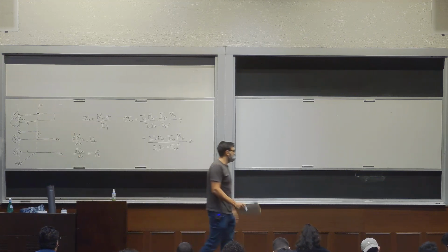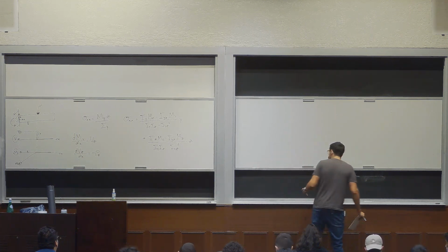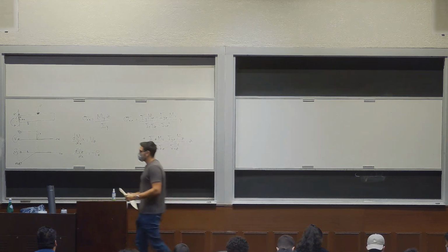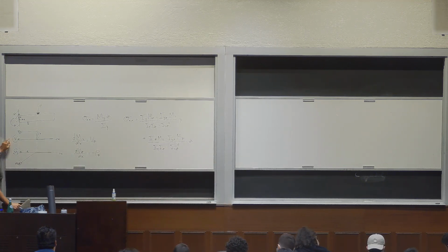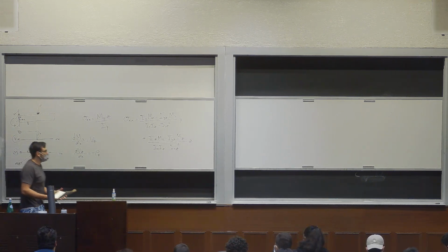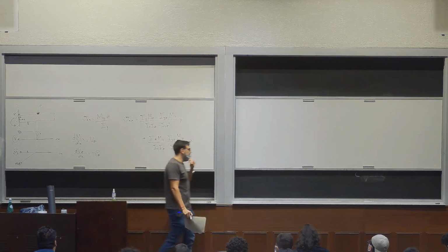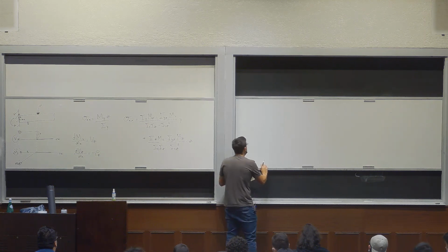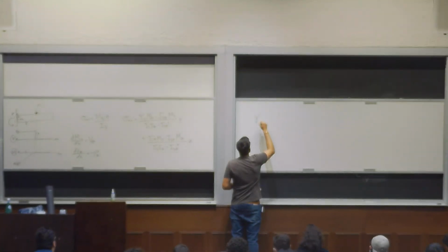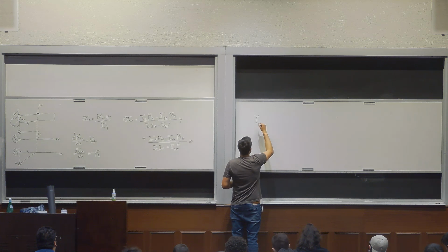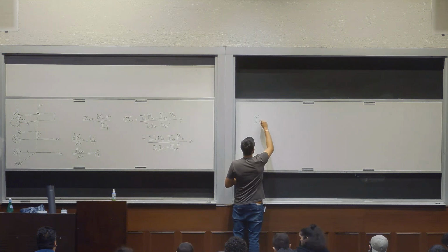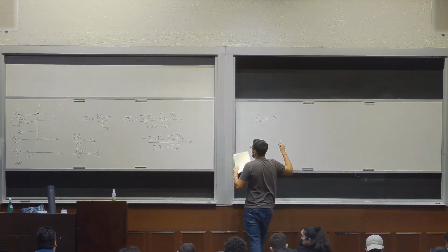Last time we talked about bidirectional bending and the normal stresses that are developed. We started talking about the shear stresses that are developed given a specific shear force, right? But we had talked about the fact that we're using this Euler-Bernoulli beam theory, and the issue with the Euler-Bernoulli beam theory is that it assumes that the shear strain gamma, xz, xy I guess, depends on how you define your coordinate, equals 0.